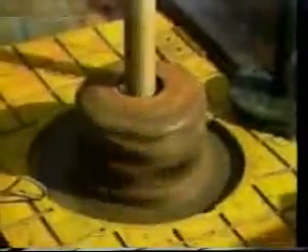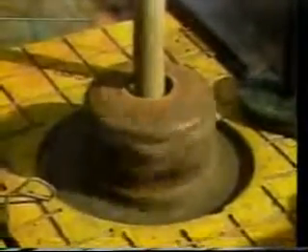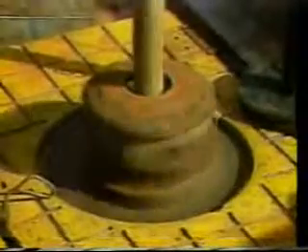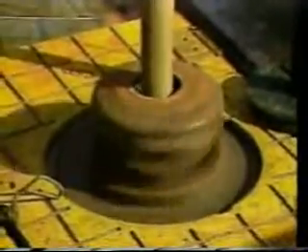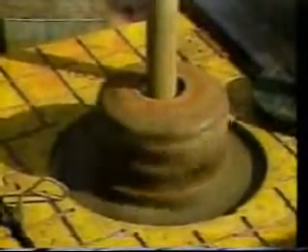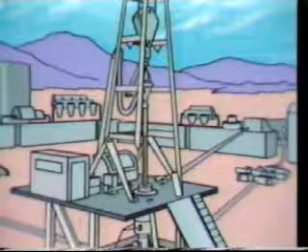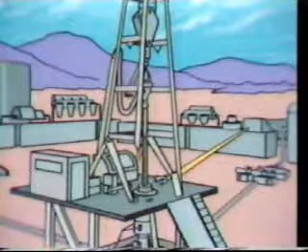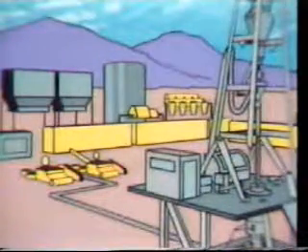Connected to the swivel is the Kelly, a multi-sided length of hollow steel which is used to transmit the rotational motion of the rotary table to the drill stem. The flat-sided Kelly fits through a corresponding opening in the Kelly bushing, which in turn fits into the spinning rotary table turned by the rig's power source. In this manner, the rotary motion required to turn the bit is transferred to the drill stem. The circulation system includes the return line, solids control equipment, the mud pumps, and standpipe.